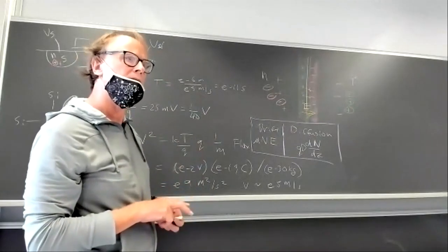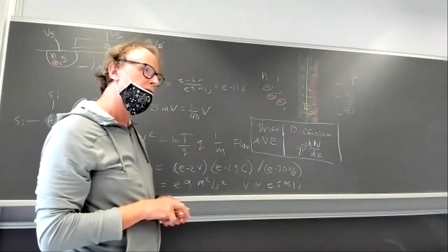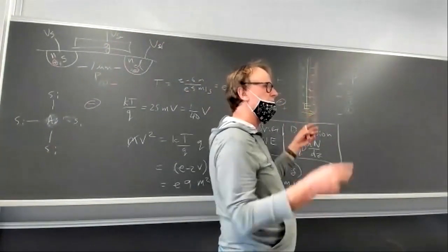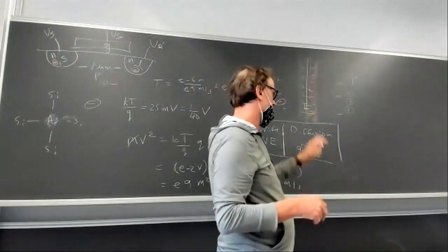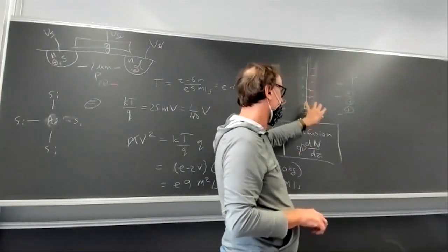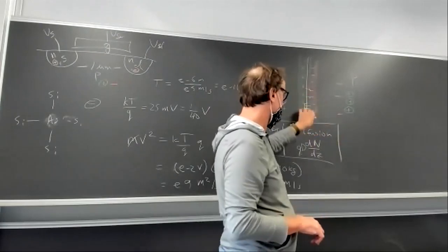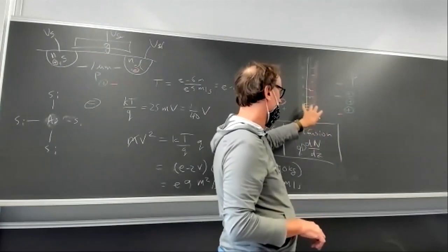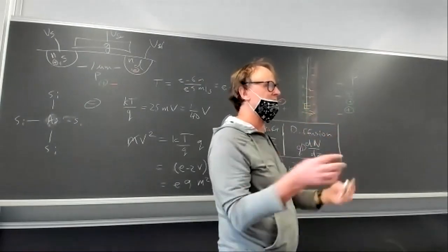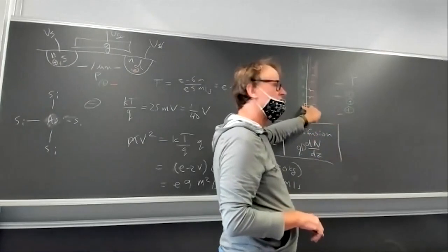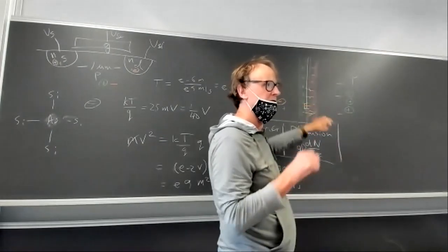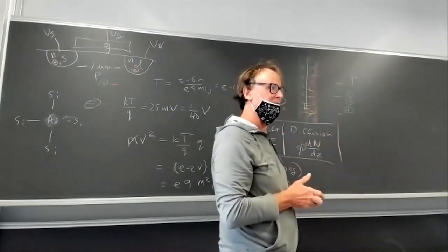And you just said that these are the fixed particles. Aren't these like the moving ones? No, there are particles that are whizzing through here, but they're in equilibrium. They're whizzing through at a high speed. But what I'm drawing here are the fixed ions. And it turns out, I'll show you in a moment, that in this region, the concentration of mobile carriers is very small because they're going at very high speed. The main charge you have here in this depletion region are the fixed ions that are left behind, the nuclei of the atoms that are charged.